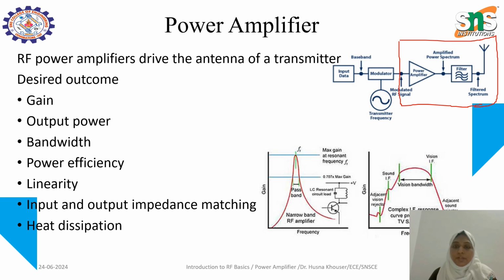Let us consider the power amplifier. The output going to the antenna is what we call Pout. We are not feeding the output of this power amplifier directly to this antenna, because the antenna impedance, let us consider, is 50 ohms, and we will not get the same power, as the impedance will not match the output of this power amplifier. That's why we have placed an intermediate filter block here.